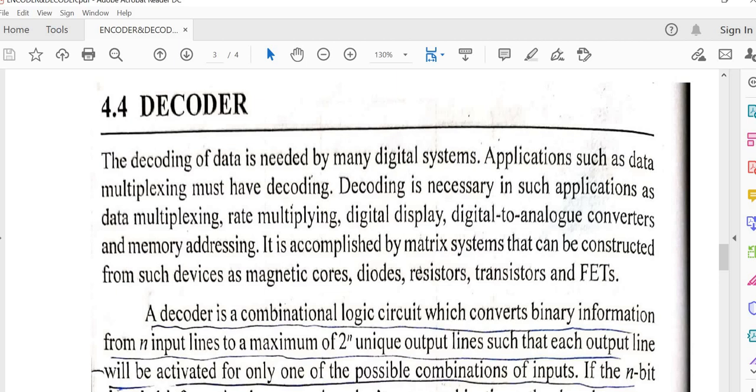Decoders are used whenever an output or a group of outputs is to be activated only on the occurrence of a specific combination of input levels. These input levels are often provided by the output of a register. When the decoder inputs come from a counter or register that is being continuously pulsed, the decoder outputs will be activated sequentially.